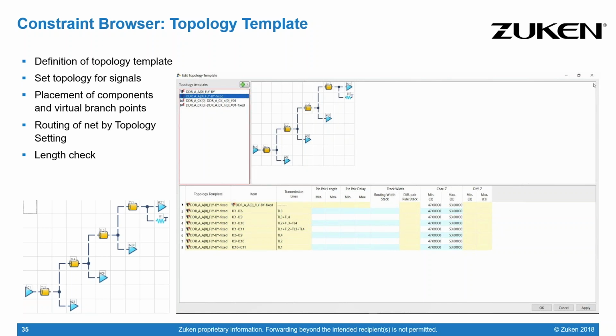So why is this topology template so important when you are considering your DDR5 layout designs? The first thing is your noise level on a trace is highly dependent on the topology you have selected. The topology template refers to the alignment order of the wiring and also the wiring structure of a network. For example, you have a multi-network load, and according to the actual situation, selecting the appropriate cabling topologies and taking the right termination is very important. And also, when we do high-speed layout designs, we have to take care of our track lengths, widths, and spacing, and that greatly reduces the effort, and configuring and managing constraints also has to be considered.